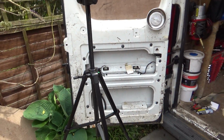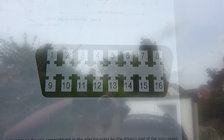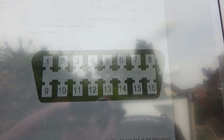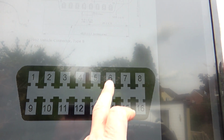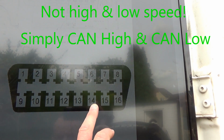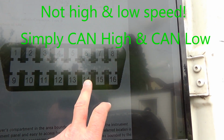So we've got my camera, got my big screen set up with the relevant information so we can see it on the big screen. There's a picture of the DLC connector. You can see top left pin 1, bottom right pin 16. The pins we're interested in today are 6 and 14, 6 being the high speed CAN line, 14 being the low speed CAN line.